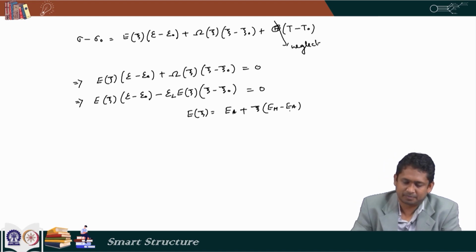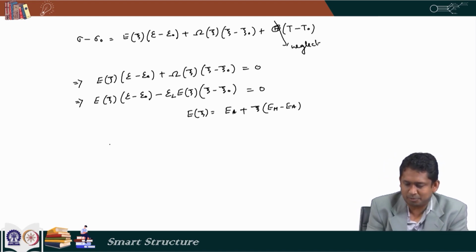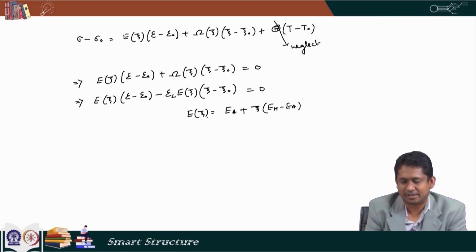So, all I have to do is using the Tanaka's model, I have to find out xi at the desired temperature for the given constant stress, and once I get my xi, I can get my E. Once I get my E, I can get this quantity which is omega, and then I put in this equation that will give me epsilon.